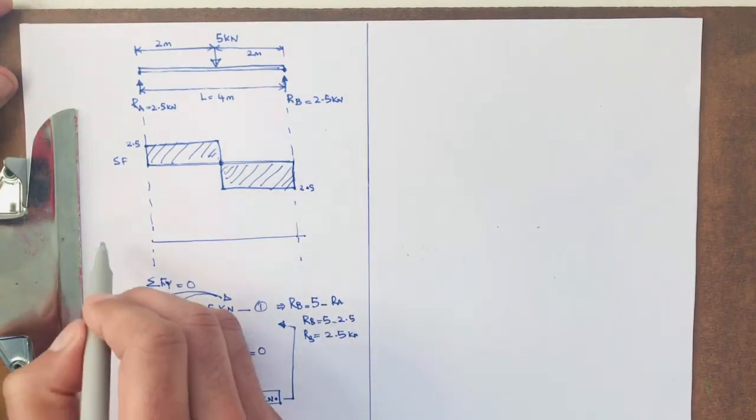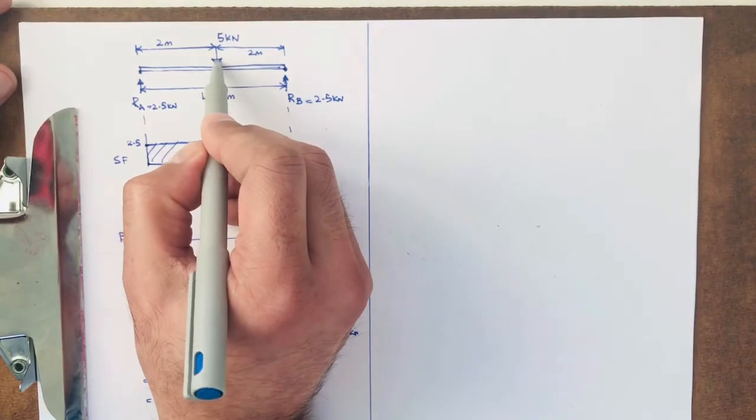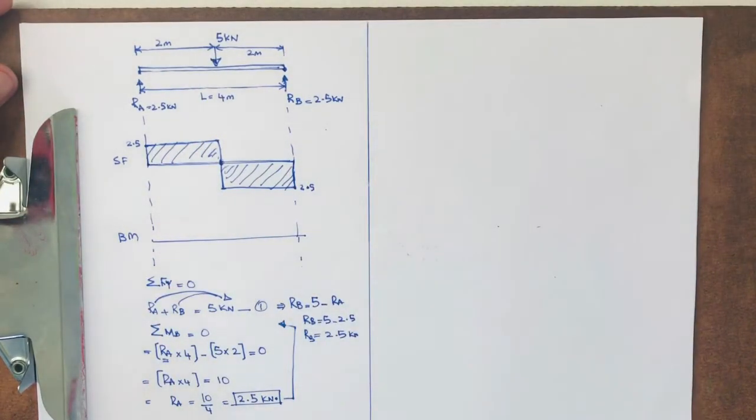So we'll draw another straight line. There are certain ways you can draw the bending moment diagrams. The easiest way, since we got the concentrated load here, is that we can straight away find out the bending moment for this case. In this case we got the point load, so the bending moment for a point load will be PL/4. That will give you the maximum bending moment in the simply supported beam for the concentrated load.